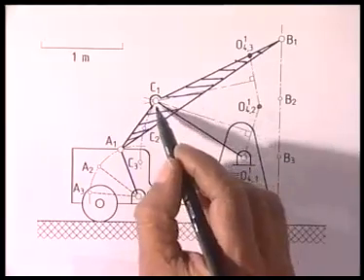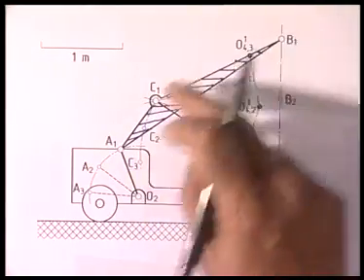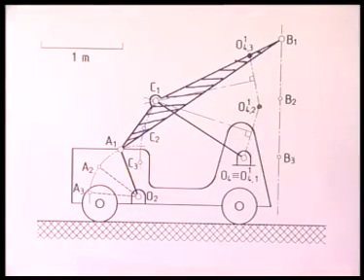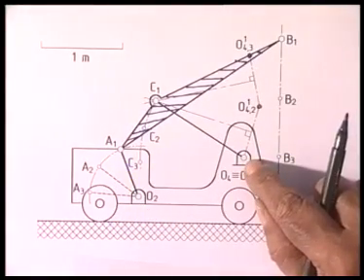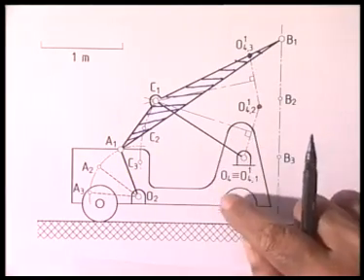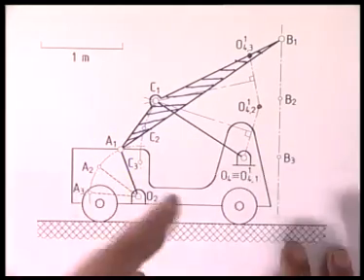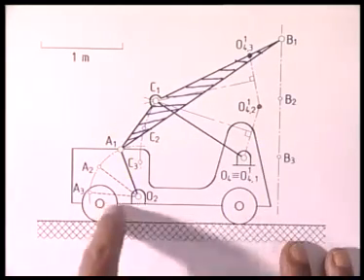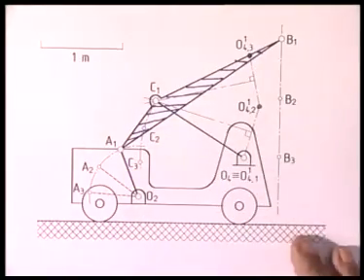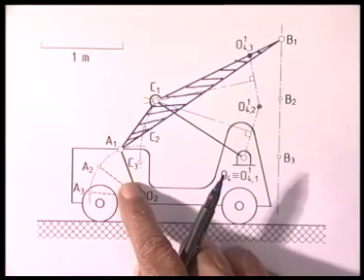Previously, the coupler was almost a straight link, and now this coupler has become triangular in shape, but we have control over the fixed hinge O4 that I can choose conveniently on the body of the truck. So, at the end of the second stage, either following the previous procedure or this alternative procedure, I can get to this 4-bar linkage with the coupler point movement coordinated with the input link.